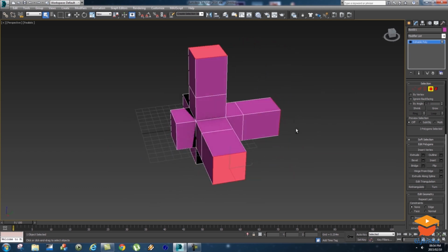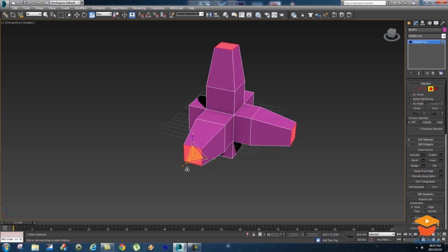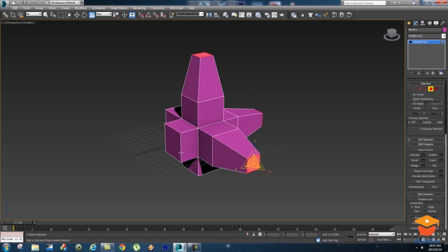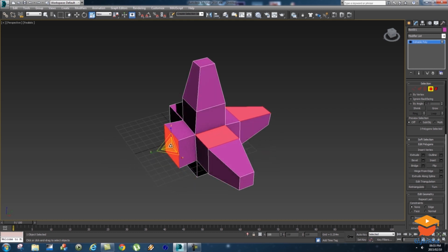and that will actually save your extrusion setting. Okay, another cool thing, let's select those 3 polygons again. So click on one, hold control, click on another one, hold control, click on another one, and I'm going to press R on the keyboard for scale, and then I'm going to scale them, and you'll see that it will scale all 3 together, which is quite cool. And let's just do some more. So this side, maybe click on that one, maybe that one, hold control, click, hold control, click. And let's scale them as well. So you can see they're all scaling together.